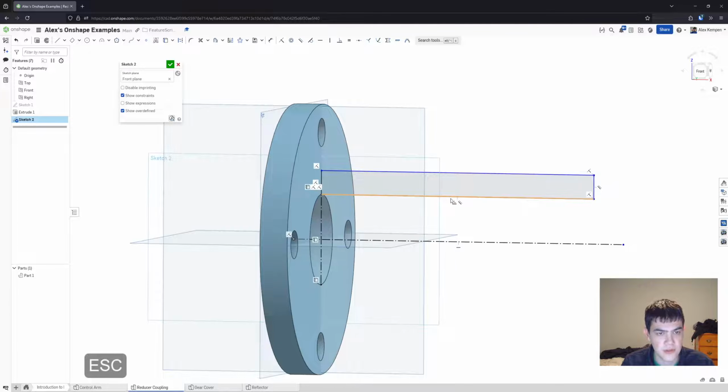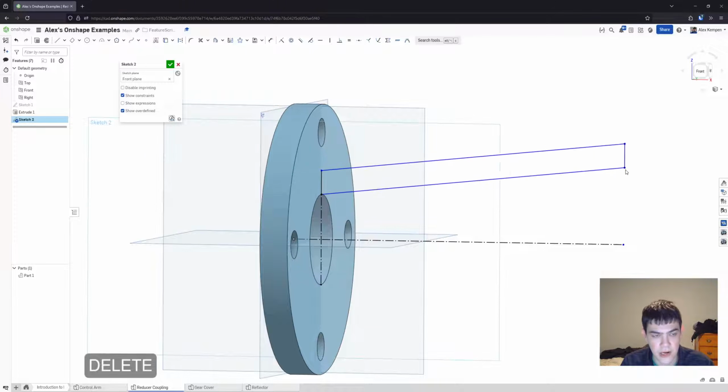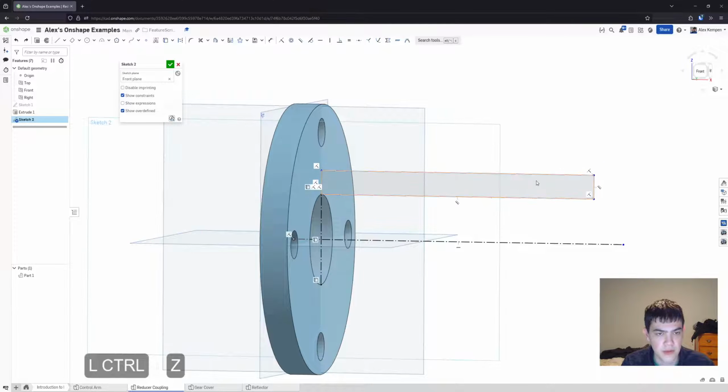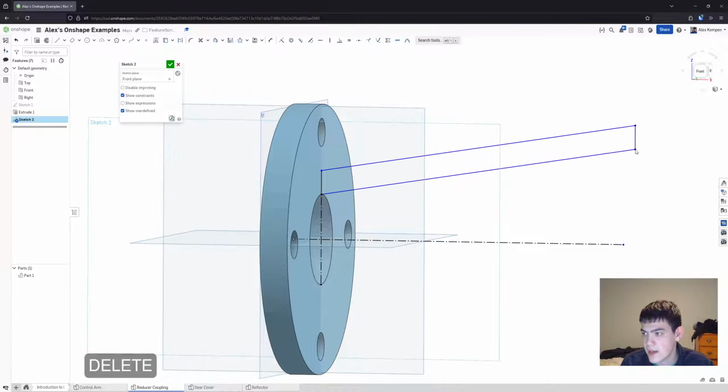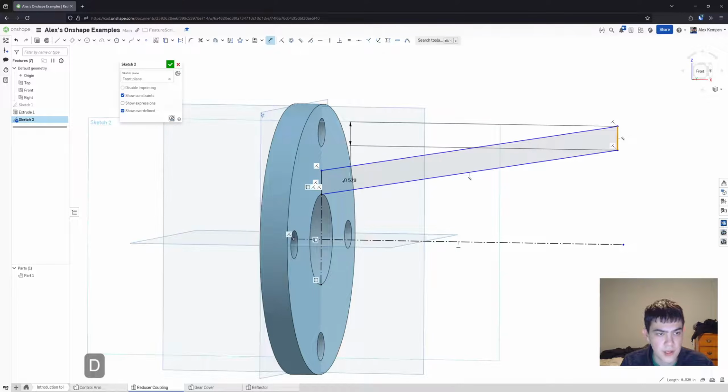And so if you were using a line, you'd probably have to get rid of this perpendicular constraint. So go ahead and convert this into a proper parallelogram, right? Because with that perpendicular, you can only do a right angle like this, which is obviously not correct. So we'll delete that, make it a parallelogram. And then you could also, of course, manually sketch a box and add the parallel constraints. That would also be perfectly fine. You can see we get two parallel constraints here and there with the aligned rectangle.